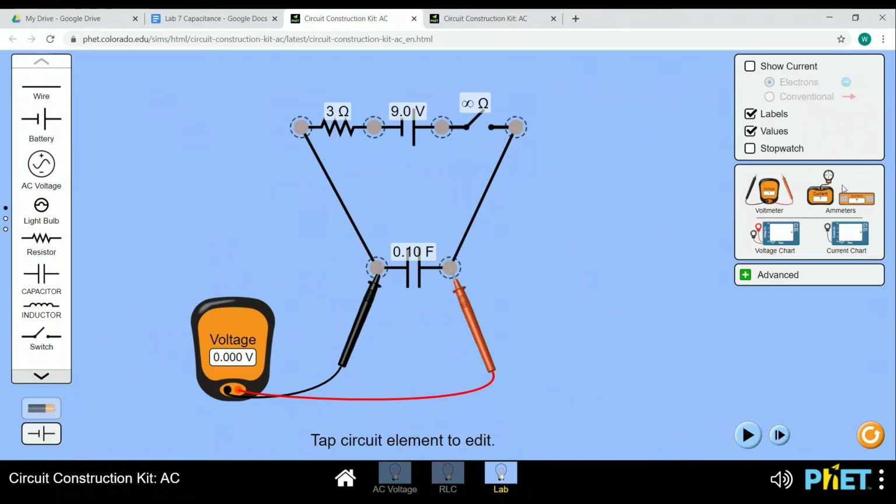And let's get a current meter in here as well. This is a different kind of current meter. The ones you're used to seeing are the ones with 2 probes, and the current passes through the meter, and that's how it's measured. But there's another way. You can take a wire with a current in it, put a ring around that wire, and it will detect the magnetic field of that wire. And then the meter calculates the current from the magnetic field that it detects. And here it's saying question mark because it's not happy. There we go, 0. No current flowing, but of course it's an open circuit.